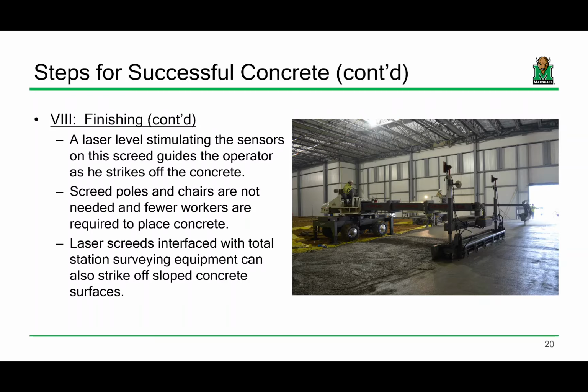For example, this would be a screeding operation in a large industrial type facility where you're going to be placing a huge pad of concrete, and you do need it to be relatively level. This can also get really technically interesting in a manufacturing setting where the floor has to be level. Something as simple as the screeding operation is going to require laser alignment and things like that.